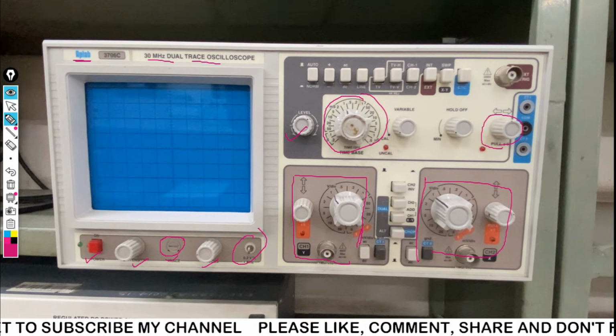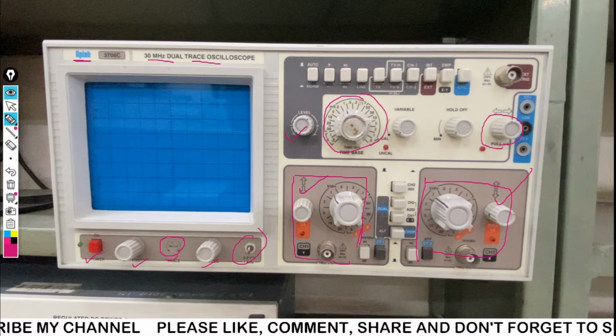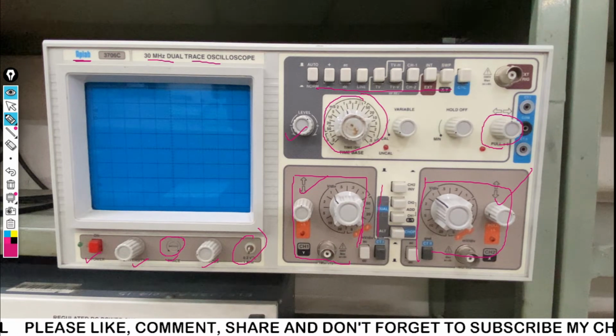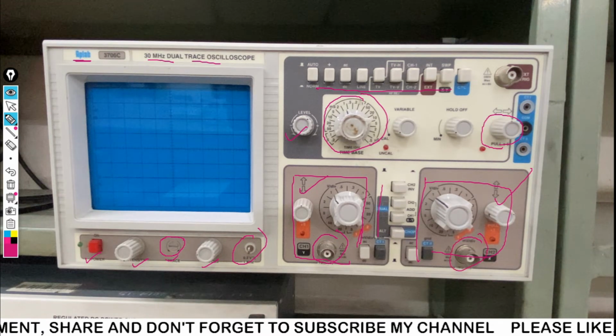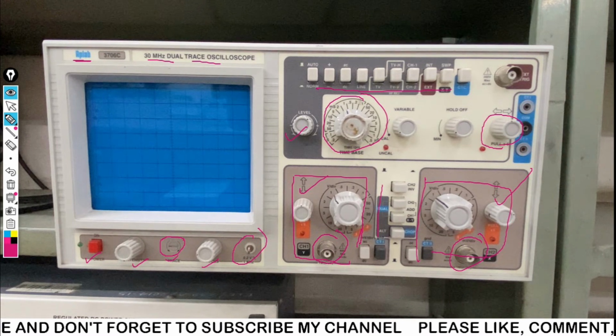This is a hold off, hold on button to make the signal hold on and off. This is for the horizontal direction, and this is for the vertical direction. You can see there are several functions available. These are also the functions available for the vertical direction. In channel Y, we can insert a signal from the external world. In channel X, we can insert signal X, and this is also for the external world.